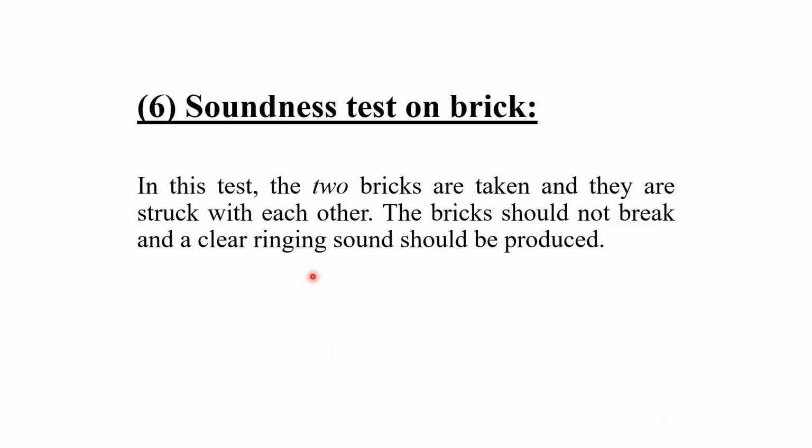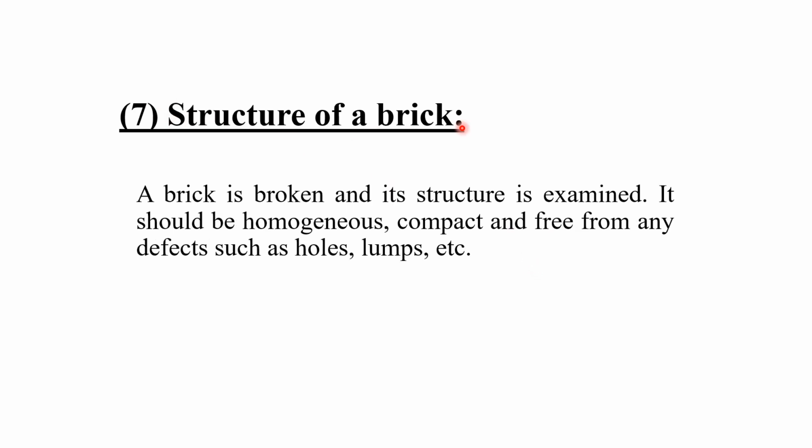Sixth test is the soundness test of brick. In this test, any two bricks are taken from the lot where the bricks are stacked. They are struck against each other. The brick should not break and a clear ringing sound should be produced. If after hitting the two bricks a clear ringing sound is produced and the bricks do not break, then that is a good quality brick. That is called the soundness test on brick.